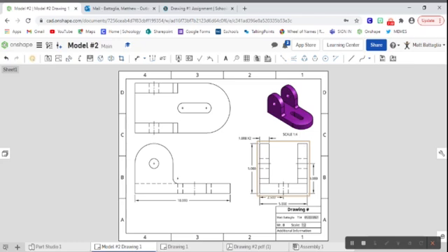We're going to do that on a few other measurements, but first let's go ahead and finish the rest of our linear measurements. So let's move to the front view, and let's find the height of our base. That'll be from here to here, scoot it out, our 1 inch right there, nice and easy.